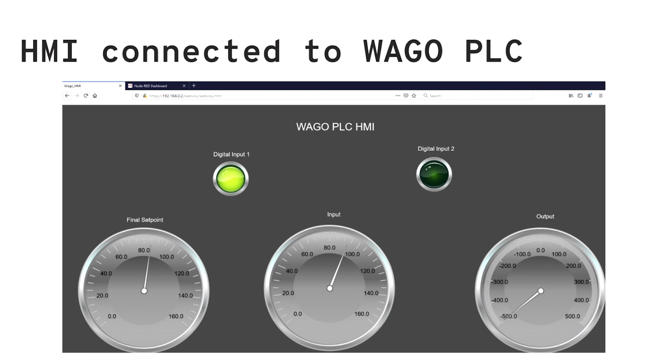And that's the benefit of the process: you don't need dedicated hardware running on the other side. You just need your TCP/IP connection and a regular browser to connect to the PLC, and you have the status of the PLC. So it's very easy to monitor that PLC because it runs its own web server that provides this visualized environment, this HMI, that provides the information the operator needs to understand what's happening in the process.